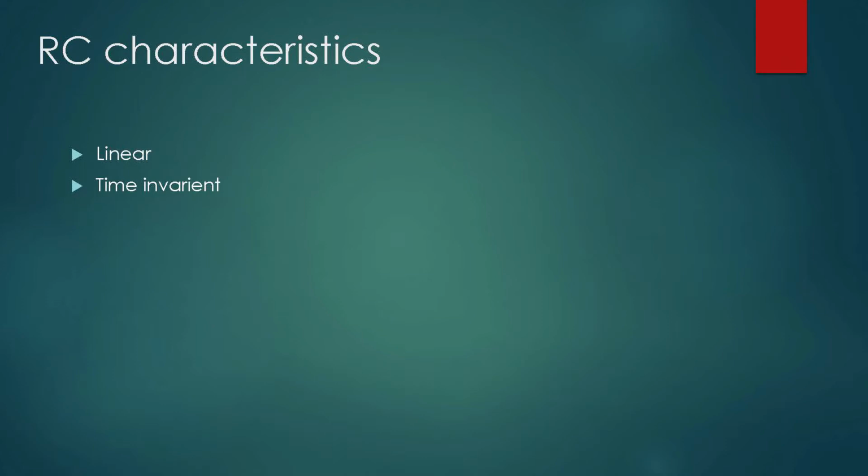The RC portion of the circuit is also time invariant. A time-shifted input to the circuit would produce a time-shifted output. Neither the capacitor nor the resistors would change the timing as the voltage and current flow through the circuit. Overall, the RC circuit and the rectifier added together would result in a nonlinear time invariant circuit.